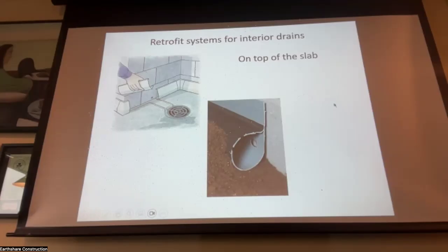Insulation on the outside, I'd say that. Where's the insulation in your wall up in the first floor? Whether it's inside or out, you want to meet those two if you can. Right. And one of the problems with exterior insulation on a foundation is burrowing animals and ants. The other is how do you connect the outside insulation to the inside insulation when you get to the sill?